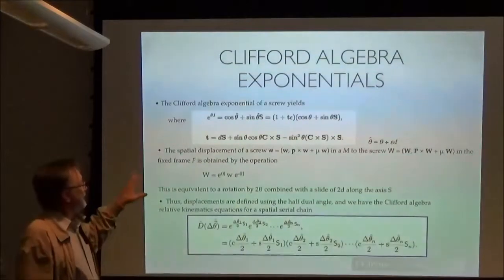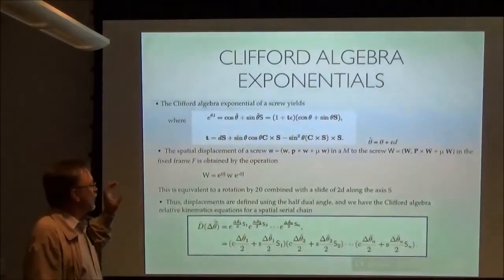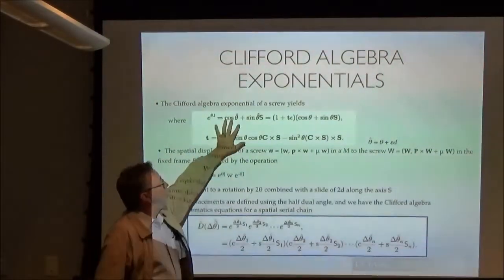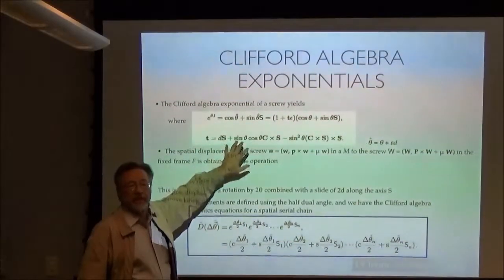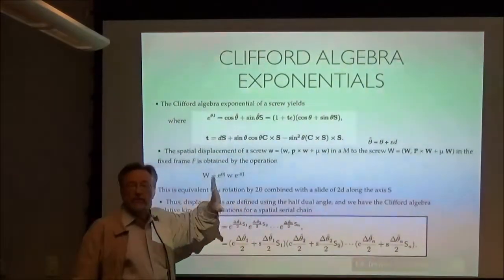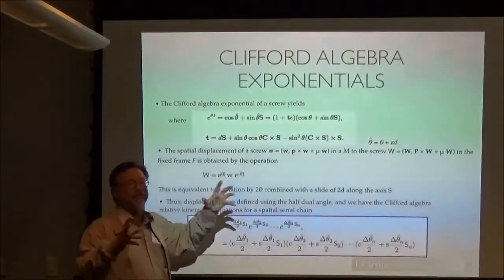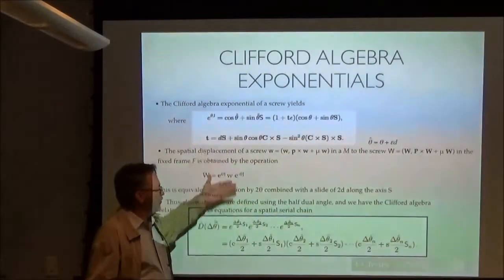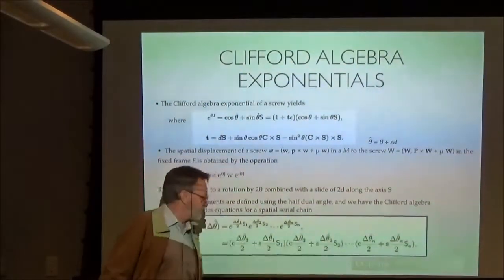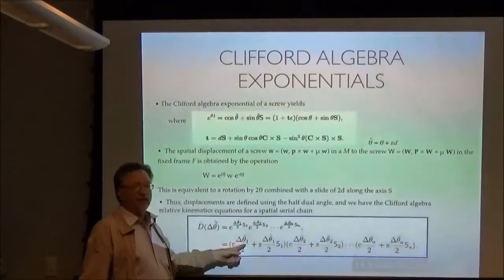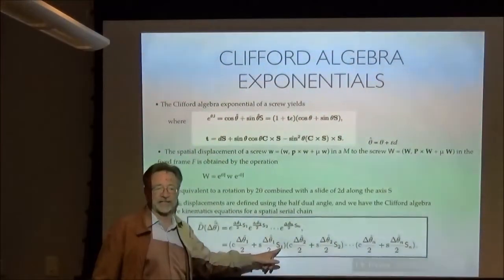It turns out that that product of exponentials matrix goes right into a dual quaternion. I mean, it's not sort of related. With just minor adjustments of notation, you get dual quaternions, where each of these quaternions is the cosine of the relative rotation angle, sine of the relative rotation angle, times the screw axis.